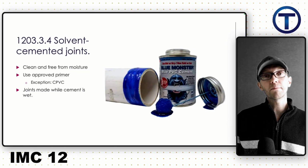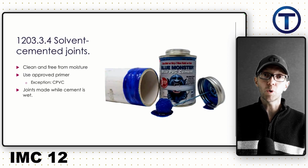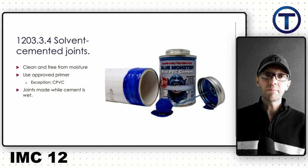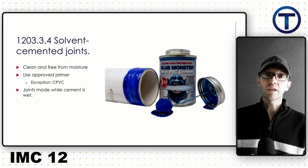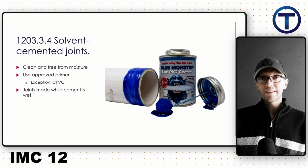Well, if you talk to the manufacturers of PVC glue and glue joints and primer, they'll recommend you always use primer because it makes a better joint. In mechanical piping, you don't have the option to not use primer because we want a watertight joint. Now keep in mind the difference.